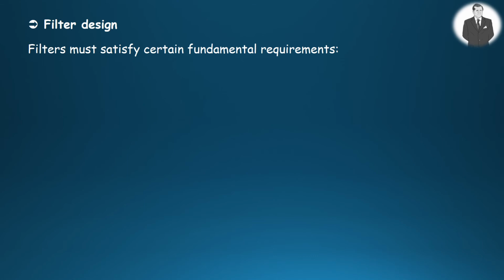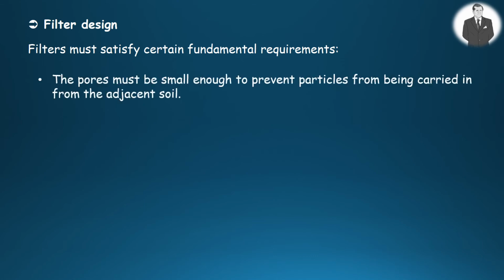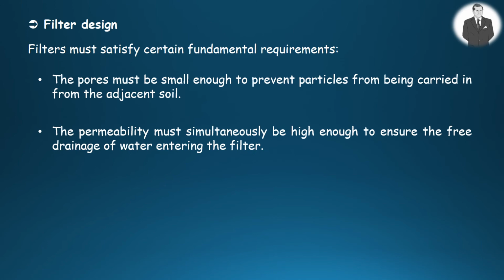Filters must meet some fundamental requirements. The voids must be small enough to prevent particles from being carried in from the surrounding soil. The hydraulic conductivity must be high enough to provide the free drainage of water coming into the filter.